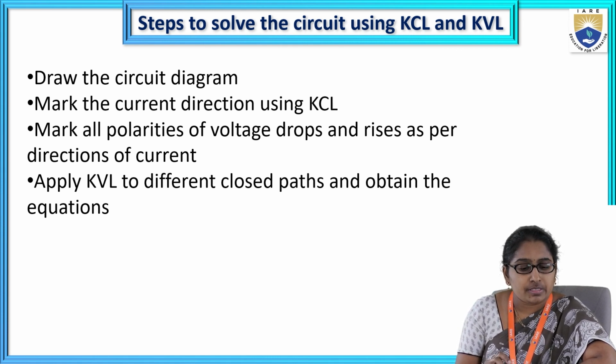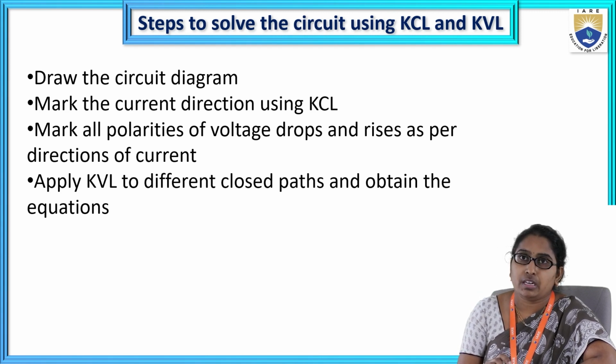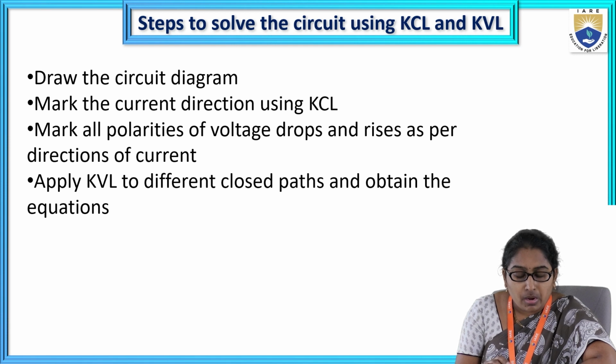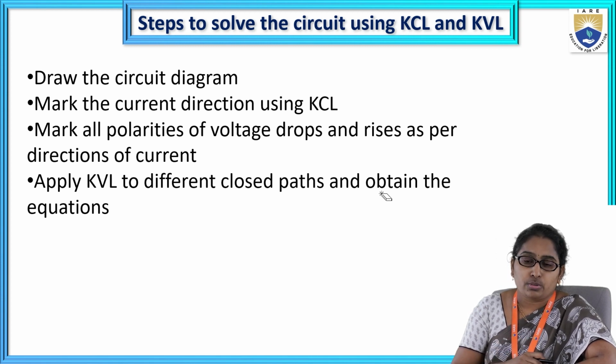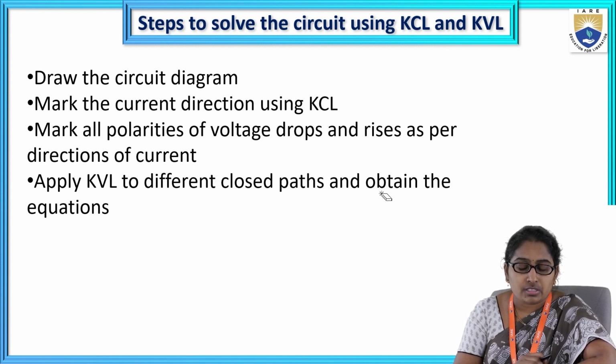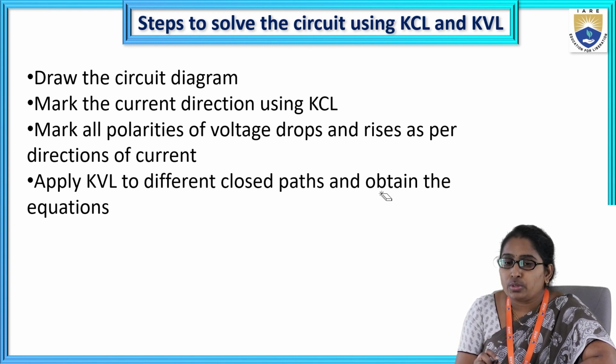Second, mark the current directions using KCL. Then mark all the polarities of voltage drops and rises as per the directions of current. This problem is based on both KCL and KVL.